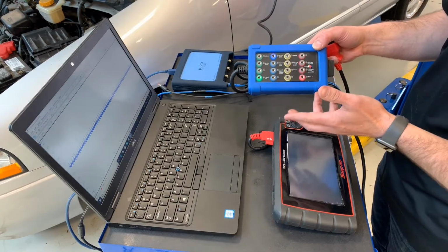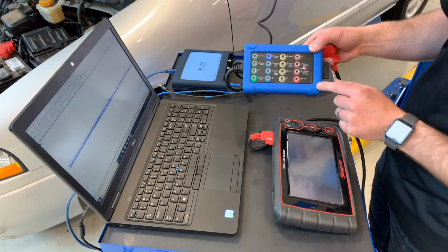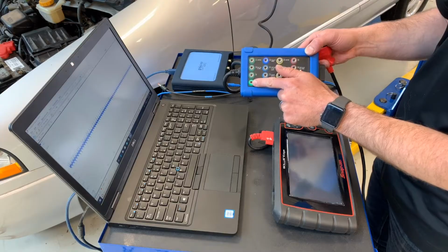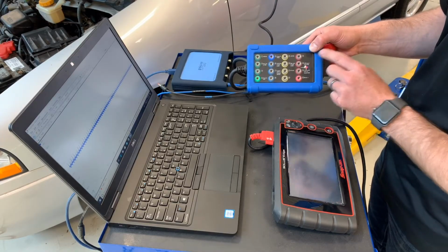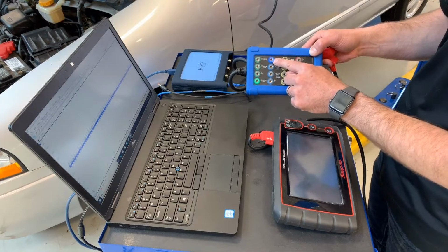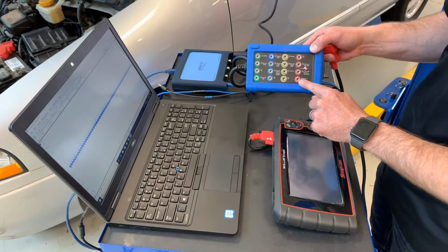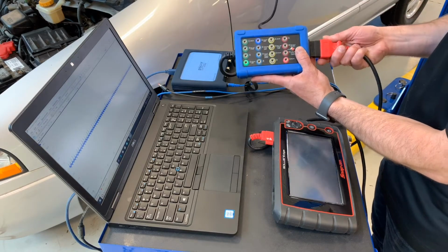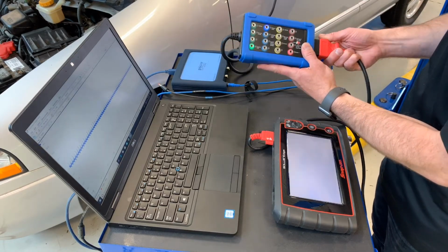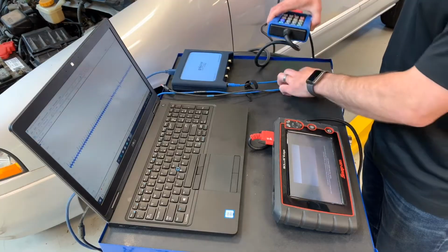The other cool upside to this particular breakout box is that I get an LED light around the ones that have activity at the time. So I can see that I've got power into it. I've got a good ground at these two ports. Pin 16 has got constant battery. And then I've got another port at the end here so I can hook up a scan tool. So I'm going to hook up my scan tool and set this aside.